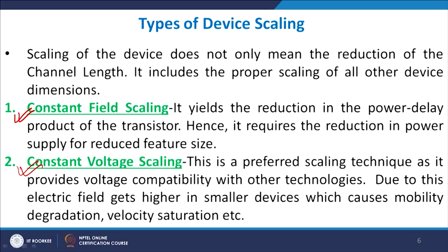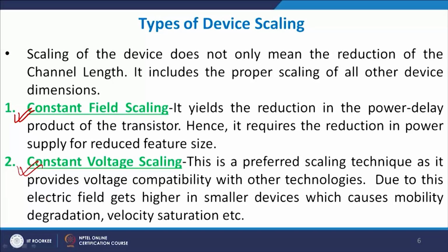Now, scaling does not only mean scaling the channel length. When you do a structural scaling, whether you scale up or scale down, you scale everything. So, you scale down the channel length, you also scale down the oxide thickness, you scale down the metal contact, the source contact and the drain contact. Everything is being scaled down or scaled up. It is not just the channel length, it is done together.